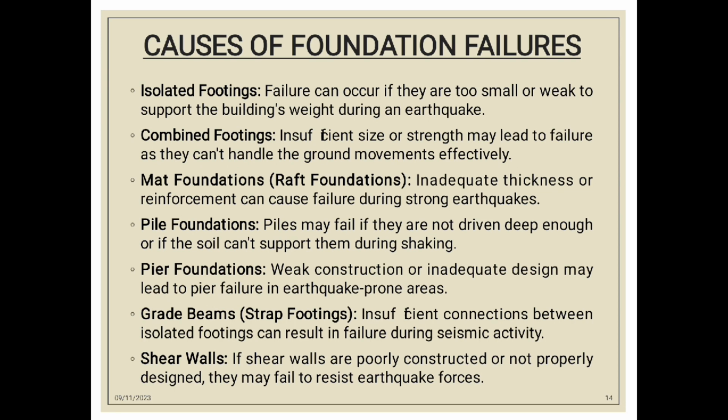Causes of foundation failures. Isolated footings: failure can occur if they are too small or weak to support the building's weight during an earthquake. Combined footings: insufficient size or strength may lead to failure as they can't handle the ground movement efficiently. Mat foundation, raft foundations: inadequate thickness or reinforcement can cause failure during strong earthquakes.